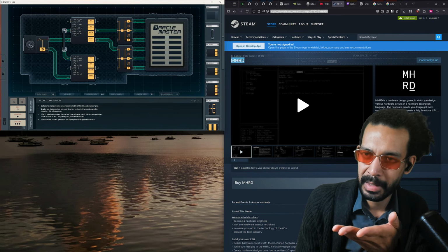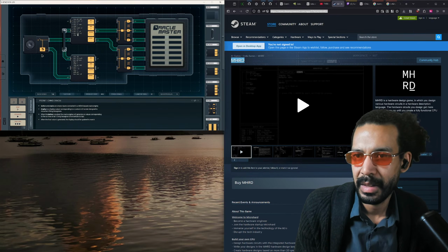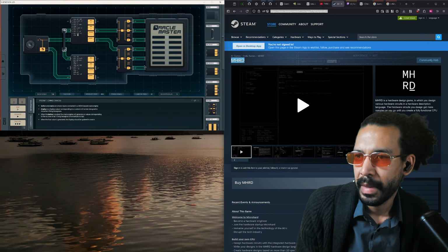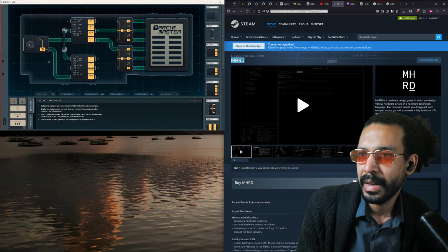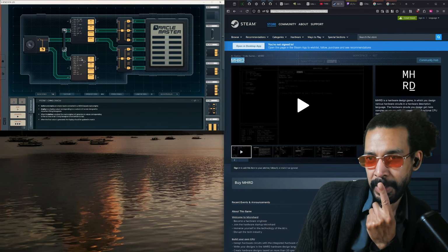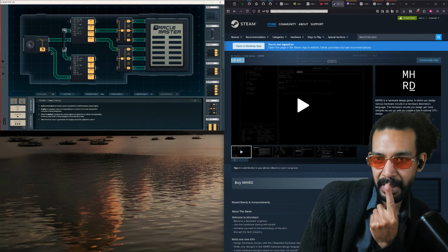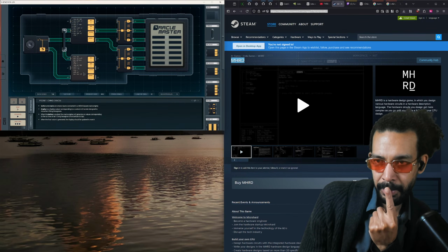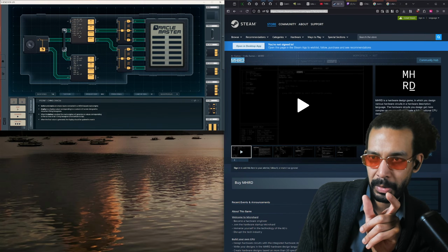Basically, every time you click a button, this generates a six-digit binary number, and you have to pass that along to this display. But not until you have all 6 digits. So what I did is I have this module here, and it extracts 3 digits at a time and passes that as one number back up to my main control module.